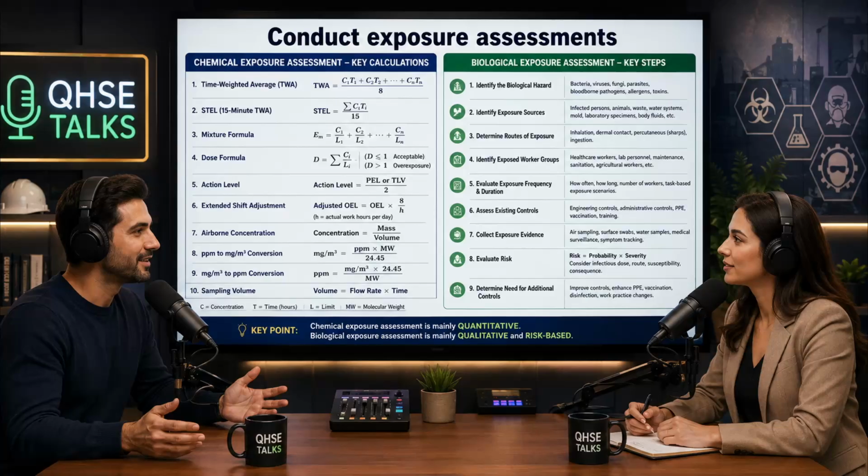Particles incredibly small, like 0.1 microns or ultrafine nanoparticles, often act almost entirely like a gas. Meaning they don't settle. Right. They're so light, they follow the airstreams perfectly, they flow deep into the lungs, but they frequently get exhaled right back out without ever settling.